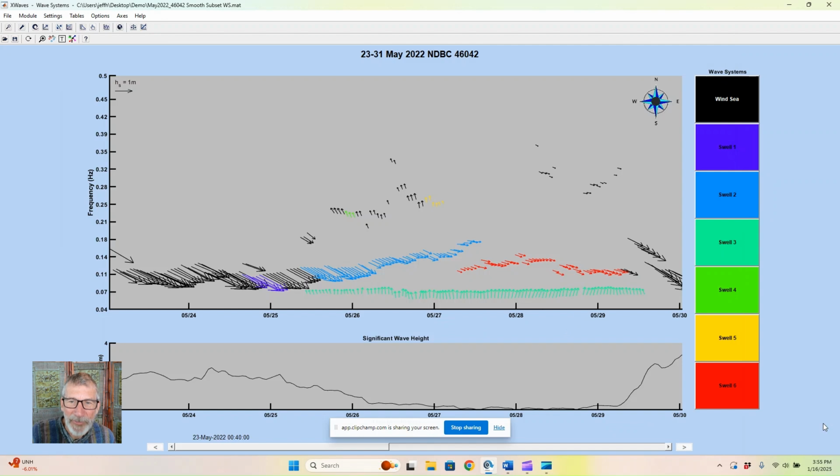Here we are back at our Wavector history map, showing the time evolution of the various wind, sea, and swell systems that have propagated through the measurement location. Of course, these waves have traveled from all types of distant weather events. But where were they? Can we estimate them? We actually can, using deep water linear wave theory, which has been built into the swell map module.